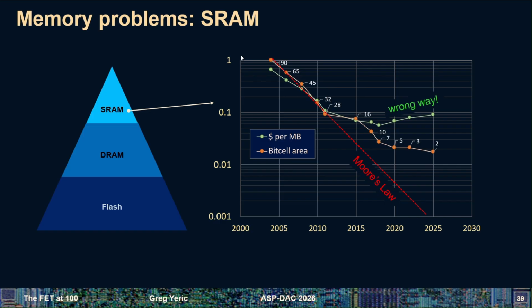What is going on there is the variation of the transistors affects how stable that flip of the logic, those cross-coupled transistors, is. It's really the variation that's the problem. So they start to vary more as they get smaller, and you can intuitively kind of understand this as the stepper has a variation. It can print widths of lines.